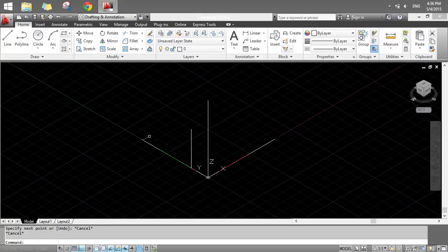Many of you might be facing this difficulty: whenever you click on the line, first of all it snaps on. Click on that point and drag it upward with your mouse, with the angle locked at 90 degrees since ortho is on, and the units increase as I drag the mouse upwards. Backspace, again mark it as 50, done.